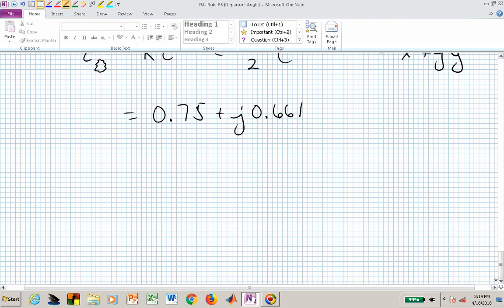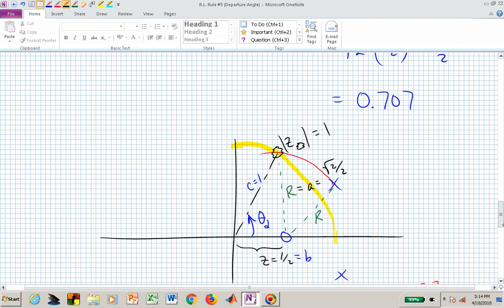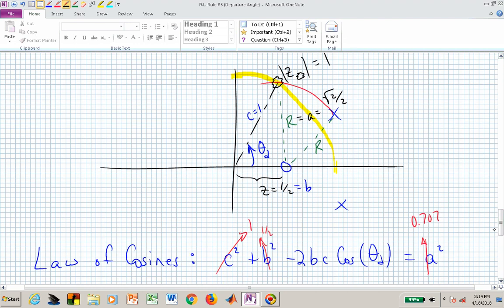And we could then calculate the gain k at that point, and doing that, we would find that this particular gain value is 0.25, and so we need to crank up the gain on our root locus to be at least 0.25 in order to become stable.